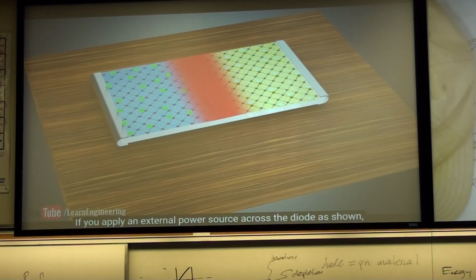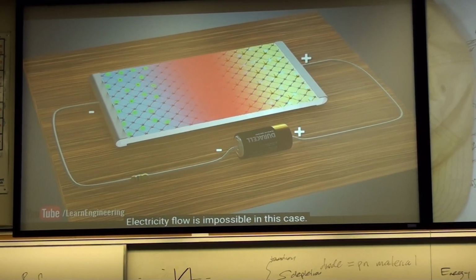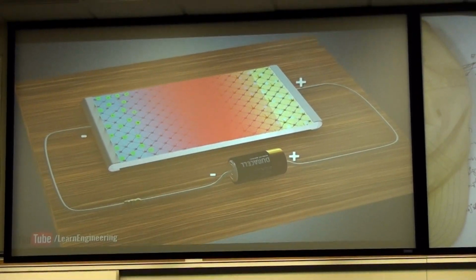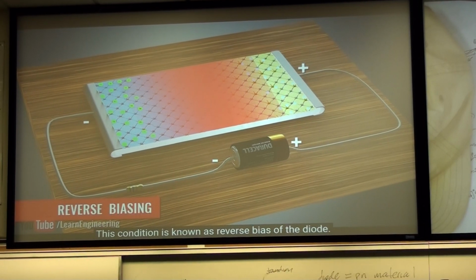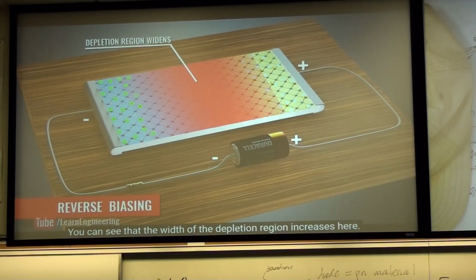If you apply an external power source across the diode as shown, the power source will attract the electrons and holes. Electricity flow is impossible in this case. This condition is known as reverse bias of the diode. You can see that the width of the depletion region increases here.